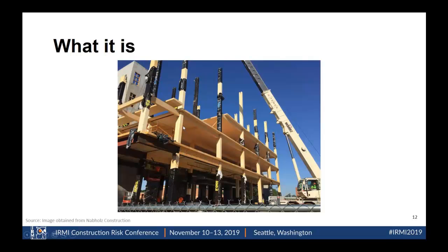There'll be better pictures in a little bit, but this gives you an understanding of the vertical columns, horizontal beams, and this is a 5-ply, 7-inch thick cross-laminated timber deck. On top of that deck, we placed a sound mat, and then we poured 1.5 inches of gypcrete for acoustics to deaden the space.